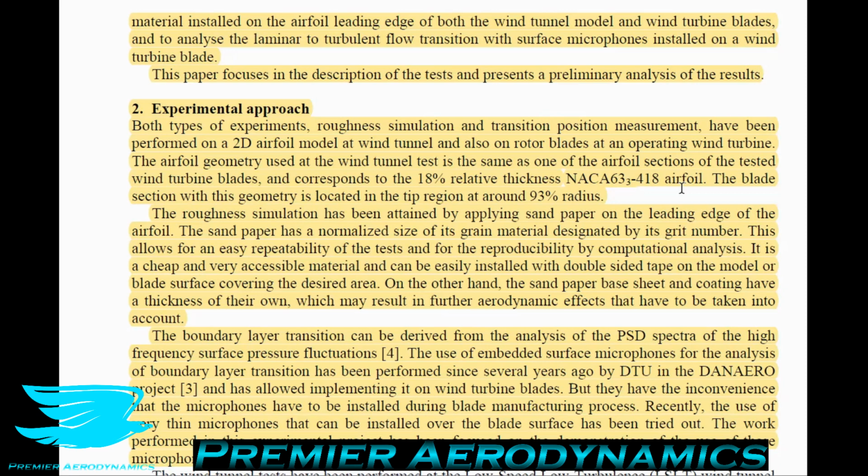So sandpaper is probably the most underrated tool that aerodynamicists can use, for a few reasons. For example, here they use sandpaper as effectively a boundary layer trip. What boundary layer trips do is introduce a lot of turbulence at a certain location, which hopefully will propagate downstream and break down into three-dimensional turbulence and just make the boundary layer turbulent. So it's very effective using sandpaper for that aim.